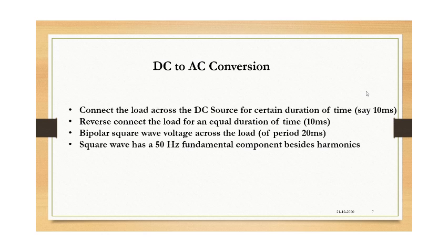I hope you are able to visualize what I'm explaining here. At the load, you will be getting positive voltage for 10 milliseconds and negative voltage for 10 milliseconds, when you connect the load across the input for 10 milliseconds, reverse the connection, and connect the load for another 10 milliseconds.